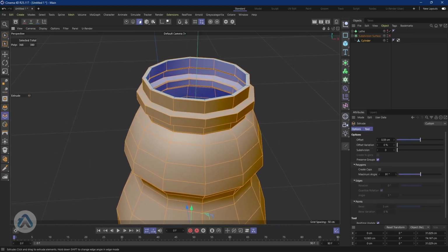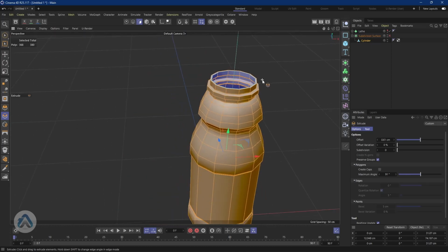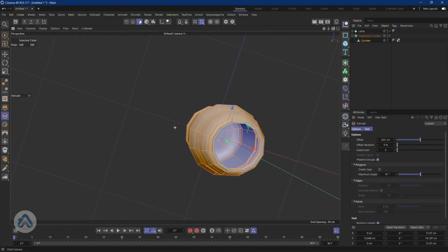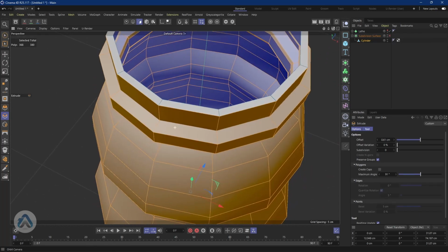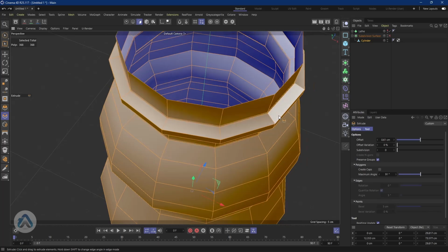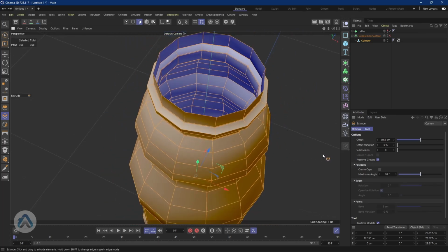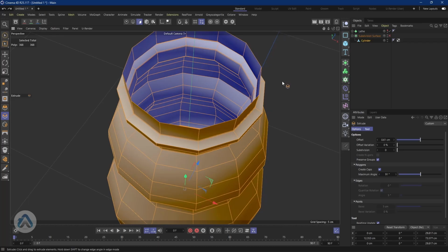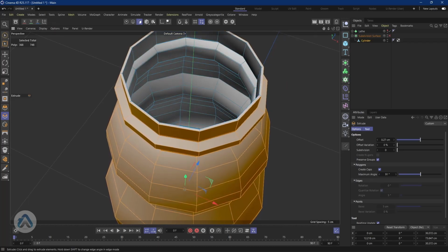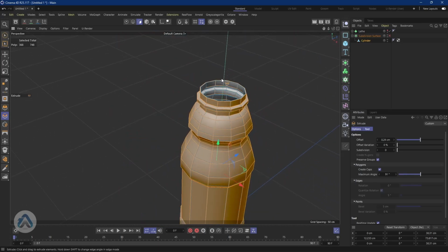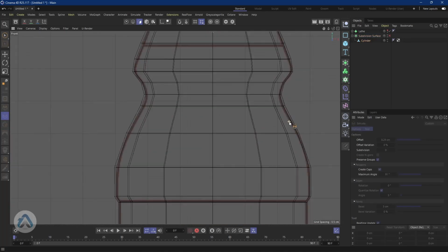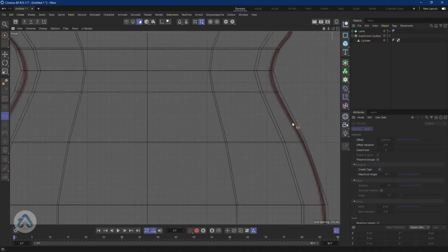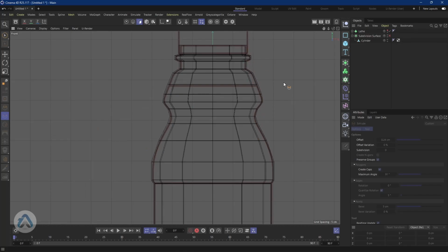When you extrude, this is how it comes. Okay, but I don't want it that way, because there will be holes inside this place that I want to cover. Okay, so let's undo it. And then when you want to extrude this, you want to create caps. Okay, so right now when we extrude, it creates caps. Now we have an inner section and an outer section. When we go back to the front view, you see this is the outer section and this is the inner section. Okay, so we now have some thickness inside this.